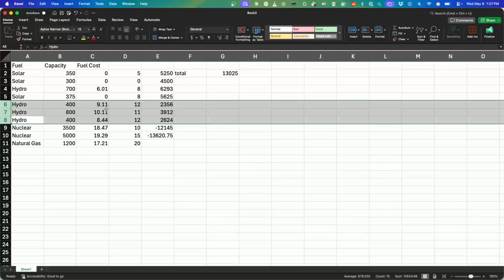And why is that? You could bid lower, right? So think about this. Let's say that the final clearing price was $10.50. Okay? That means none of these three generators would have turned on, right? Because their bid price was higher than the clearing price. But if it was at $10.50 and they did turn on, they would have made money. Okay. So it turns out the optimal strategy is to actually bid in at your operational cost, right?